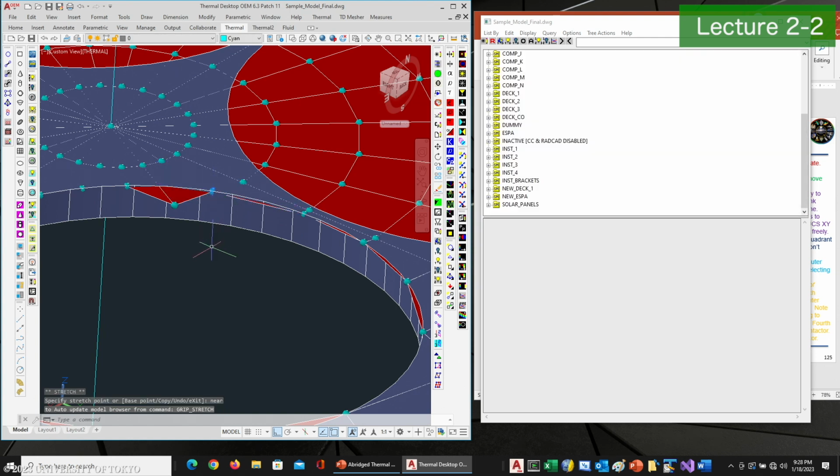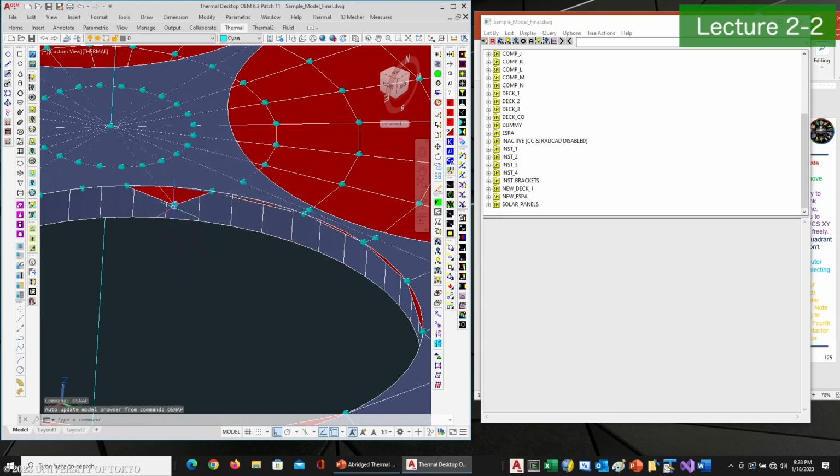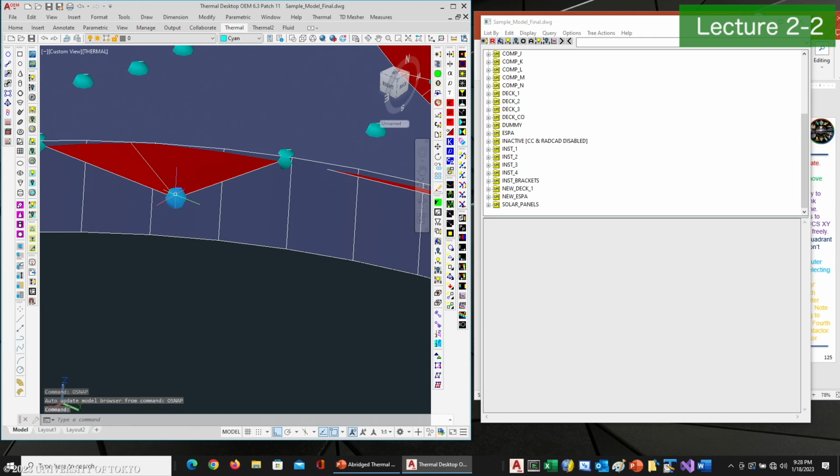That's one other thing. There's an OSnap, object snap, which you normally have on. And so these are all the different types of things that we'll look for. So if I were doing this a whole bunch, I could say, you know what, I want to add nearest to it and hit OK. So now as I click on this, there, near will show up here if it finds nearest being the closest thing, so that I don't have to keep typing in near every time.